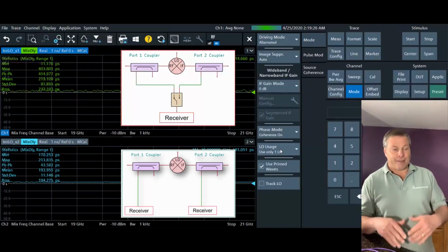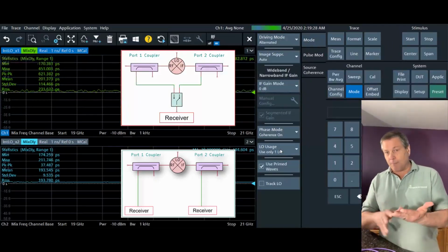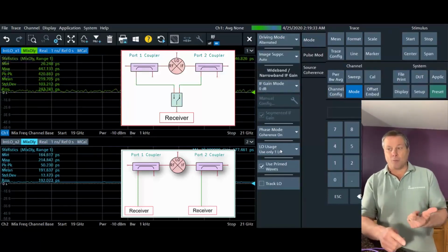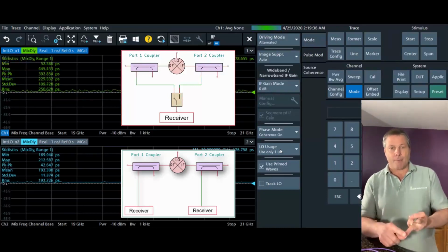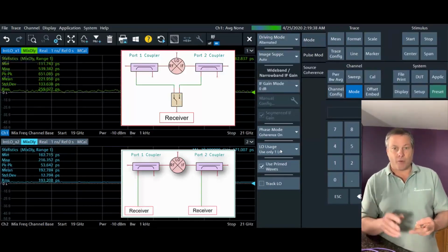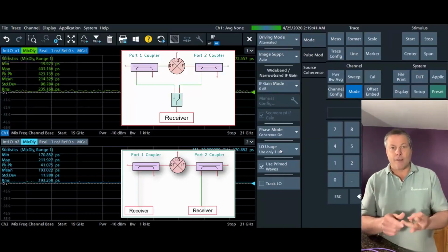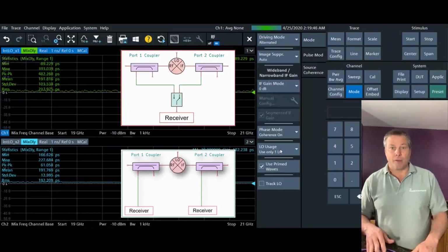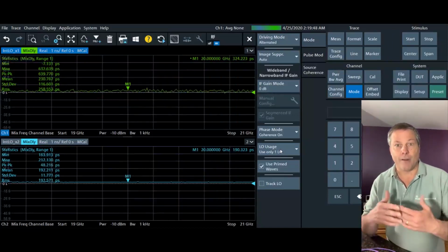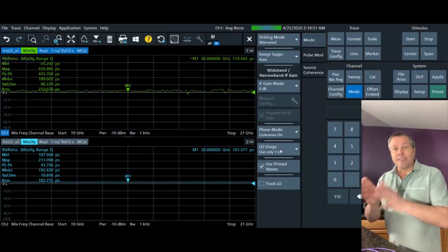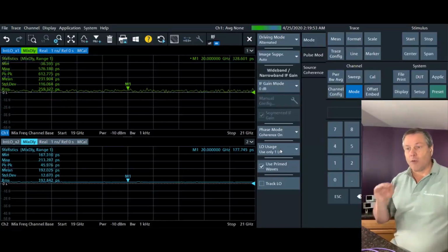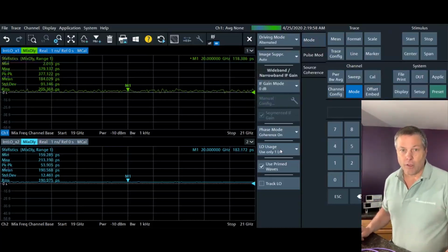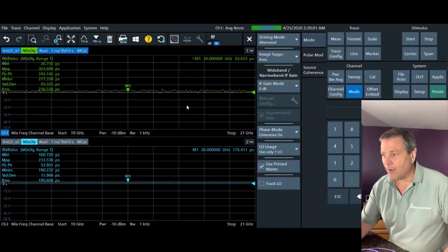Now also keep in mind, this is idea number 8 on my list. That means I've already implemented the first 7 ideas, and we're taking advantage of all of them, which is automate the measurements so I don't forget any settings, optimize the power levels for both my receiver and my transmit signal coming out of the network analyzer, optimize the tone spacing, optimize the resolution bandwidth, pick the best averaging possible, and so on. I'm already forgetting what all the ideas were, but I'm taking advantage of all these things already, so my traces are looking really good right now before I even take advantage of the 2 internal local oscillators. But let's take a look now at what it looks like.